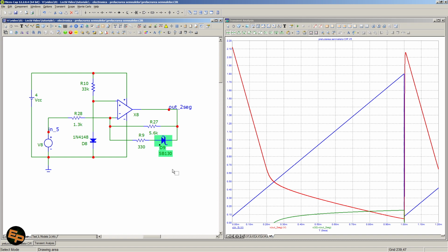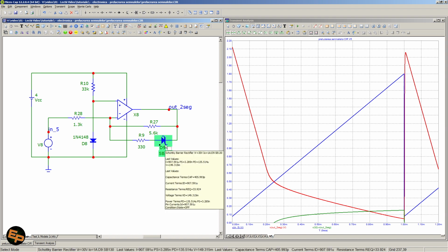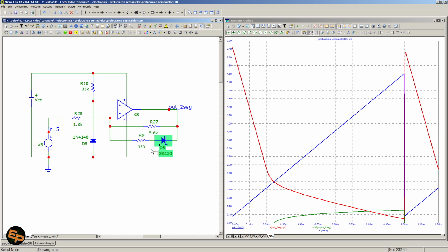It doesn't have enough voltage across it to start to open. Starting from that point, when the diode starts to conduct, it will place this much lower value resistor in series with this one. This lower value resistor will dominate essentially, and so the overall amplification factor will diminish a lot.